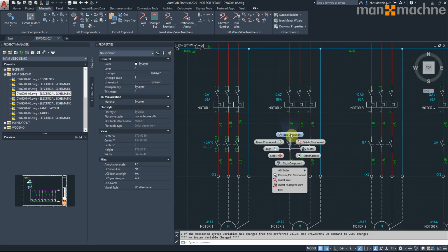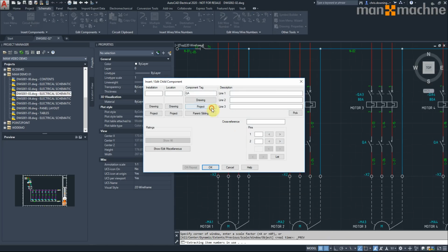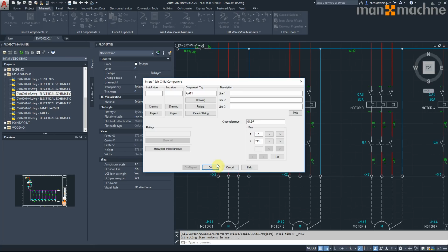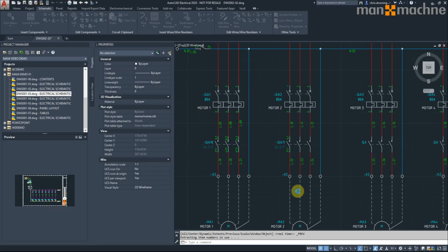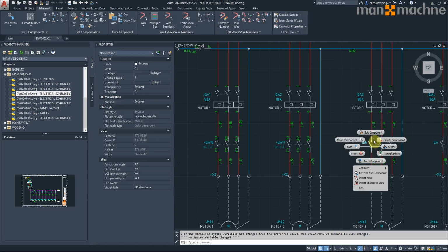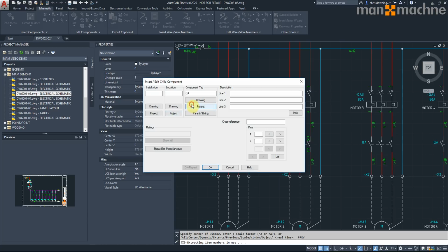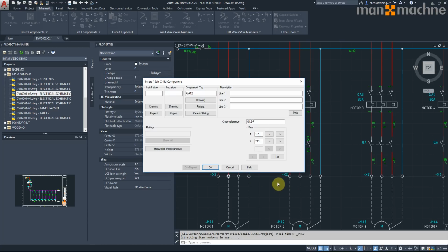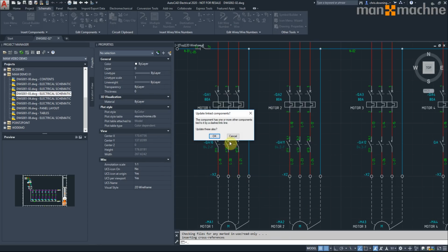The pin numbers are related to the particular catalog information that I've put into the coils. The catalog information was placed in the circuit in the previous project where I've copied the circuit from. So when I copy a circuit, I don't have to re-enter all the catalog information, providing it's the same catalog information as it was on the previous project.